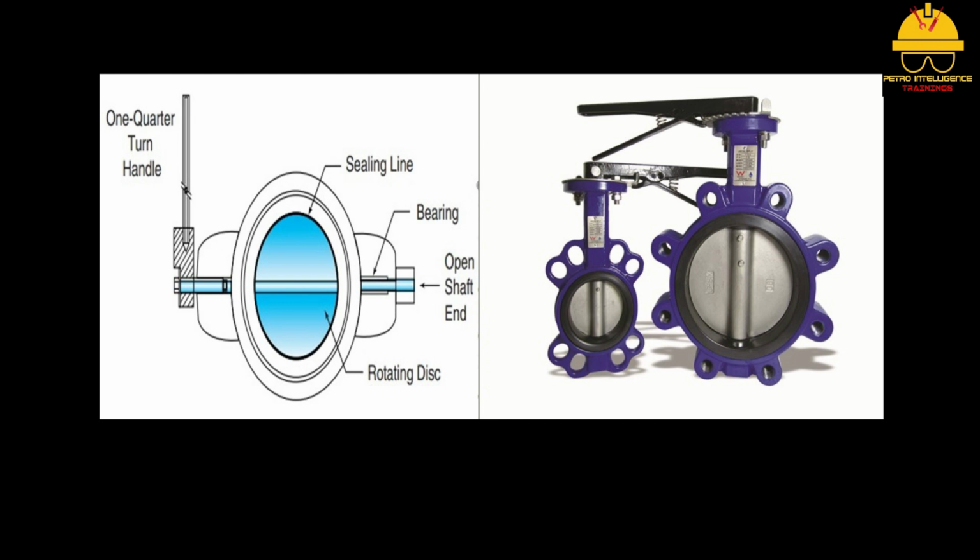Technicians should be aware that butterfly valves are 100% open shortly after the valve handle passes 1/8 of a turn. During a throttling operation, a butterfly valve handle should be carefully secured. As flow enters the body of the valve, it contacts the disc and will cause it to open if the handle is not latched into position.